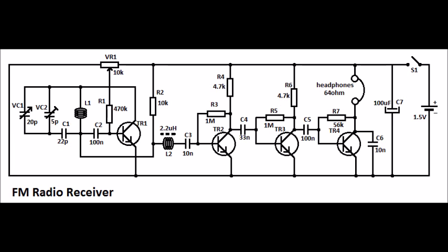So what we do is we take the signal from the local oscillator and pass it through the mixer along with the signal from the antenna, so that the required signal that we need becomes 150 megahertz. On passing this mixed signal through all three filters subsequently, we slowly remove all other frequencies, which act as noise in our case, and finally what we have is the signal that we require at 150 megahertz, which is then decoded and sent into the headphone.